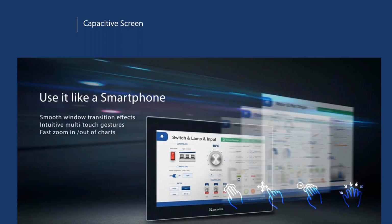For example, I can define that when I use 3 fingers to swipe the screen from the left side to the right side, the HMI changes a PLC register's value and also changes the window at the same time. So you can use touch gestures to do many different, complex actions, just like using the buttons on the HMI. This is our capacitive screen and touch gesture.